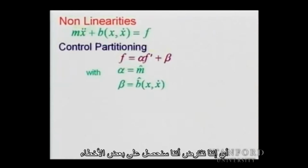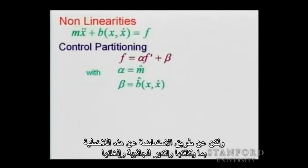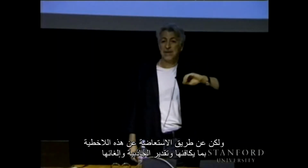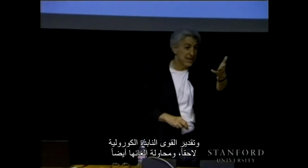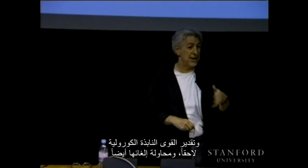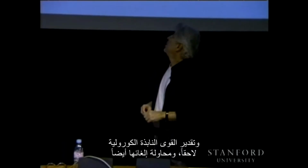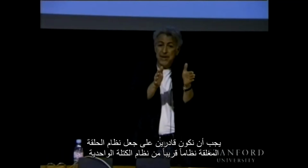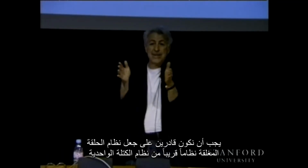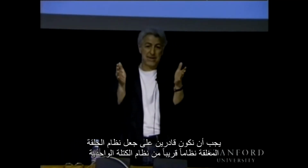So we're assuming that we are going to have some errors, but by compensating for those nonlinearities, estimating the gravity and taking it out, later estimating centrifugal Coriolis forces and trying to take them out, we should be able to bring the closed loop system closer to a unit mass system.